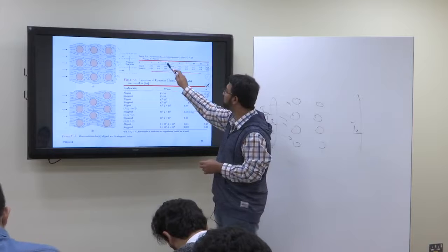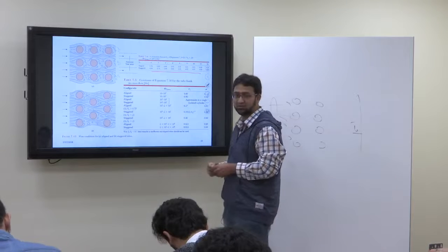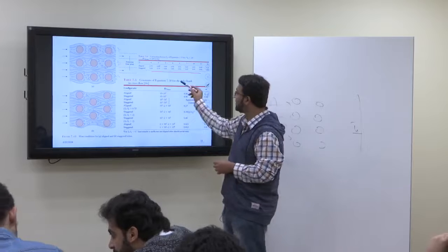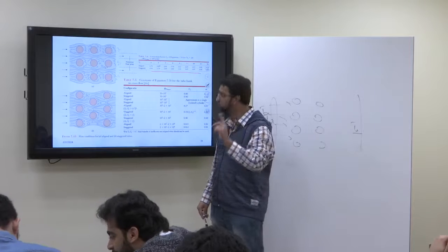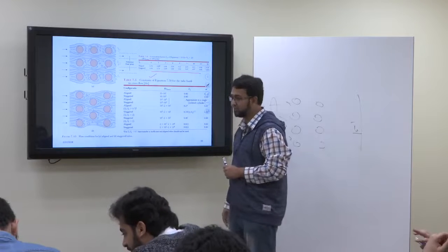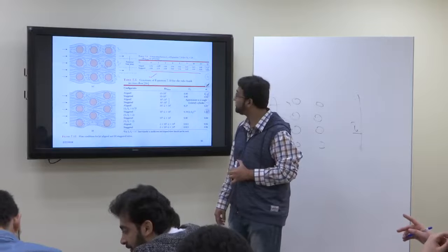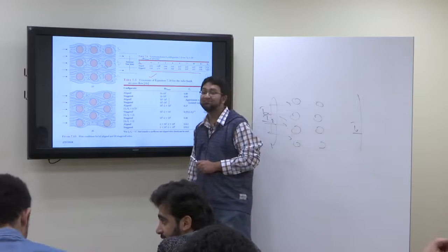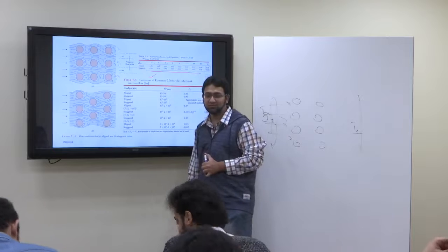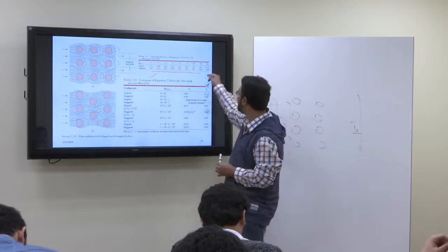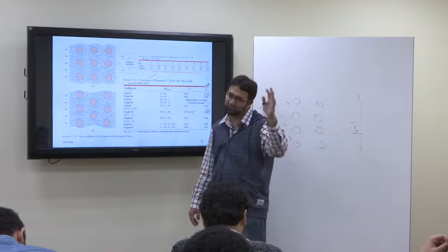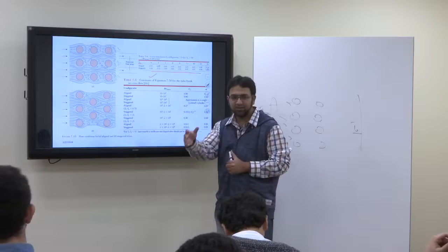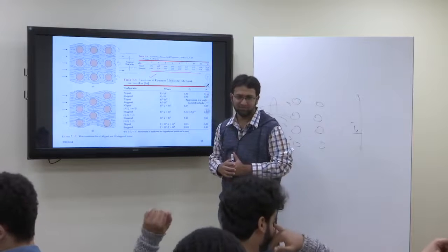For 1 tube row, 2, 3, 4, 5, 7, 10, 13, 16: if it is aligned, these values; if it is staggered, these values. Similarly, for the values of C1 and m, you will use table 7.5. Here NL is the number of tube rows. For about 17, it is 0.99, so consider it as 0.99 from 16 to 20, because at 20 it will become 1.